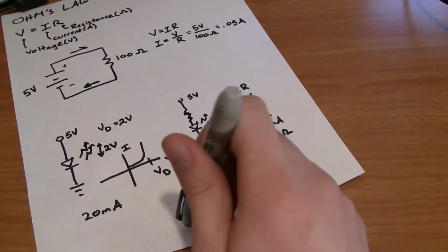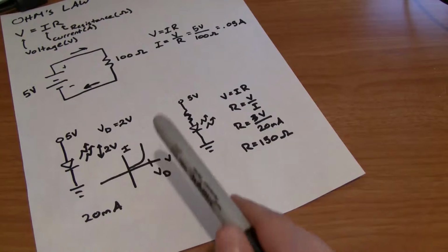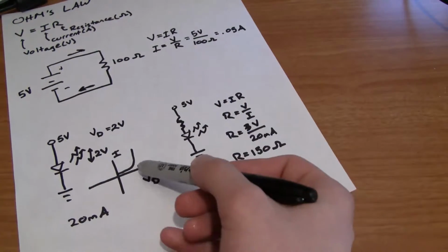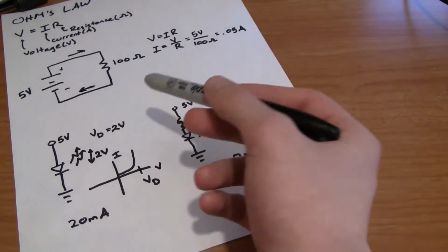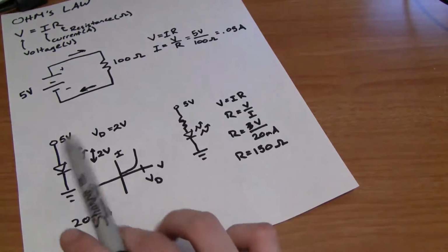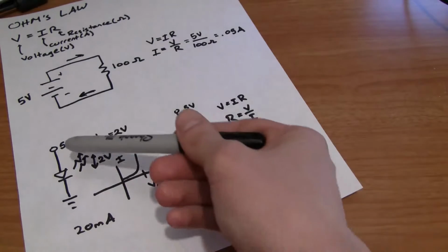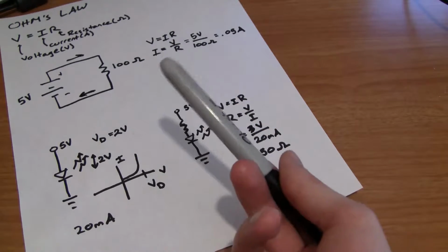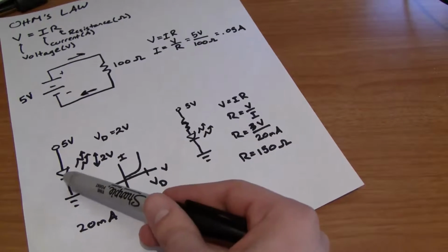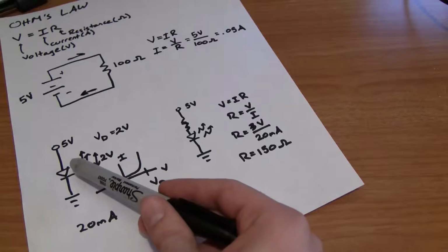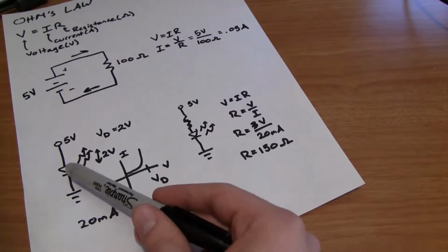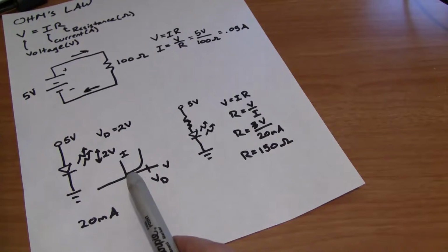The way LEDs work is they work on a diode IV curve, which you can see here. Basically what that means is that after V drop, or after a certain point, the diode allows any amount of current available to flow through it, which is good for many circumstances, but if it's a light emitting diode, or any diode really, we're going to have an issue because we're allowing it to draw unlimited current from the source. And the Arduino supply can only store so much current. So this is going to suck up all the available current, and it's going to kill your battery very quickly, and the LED is going to burn very bright but also get very hot because you're sending so much current through it, way more than it's rated for, and that'll kill the LED pretty quickly. So it will light up, but we're going to run into some issues.